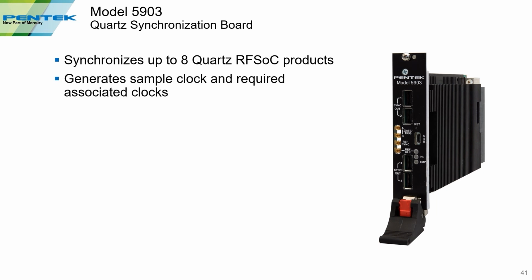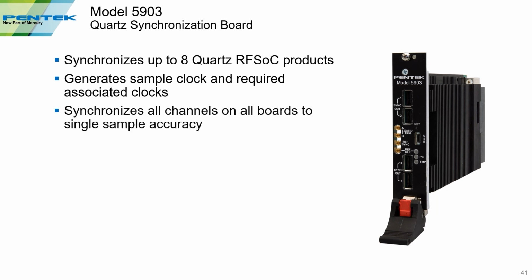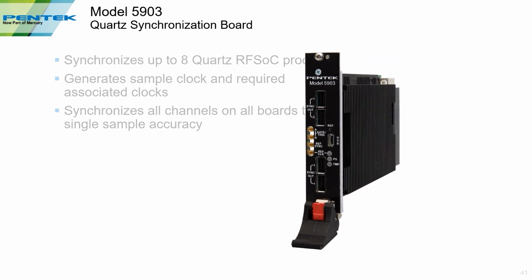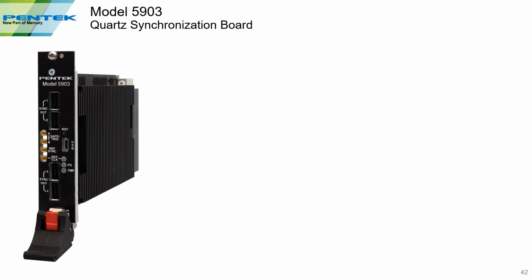This board generates the sample clock and all the associated clocks that you need to do multitile synchronization. So that's all generated locally on this board, and it synchronizes all the channels on all the boards to single sample accuracy. And again, that's critical for doing things like beamforming.